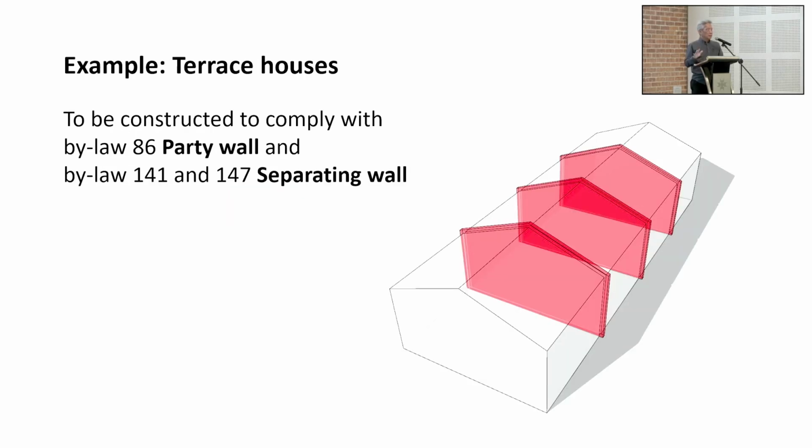But to summarize, to make it very, very simple, take for example a terrace house. For a terrace house, there are no compartment limits to a single residential building, right? Doesn't apply, no compartment limits. So there are no compartments in a terrace house. Inside it will all be partitions only, and you don't have anything in your house that will be picked up by UBBL 139, is it? You're not going to have lithium ion storage, an ESS room in your house, right? Nowadays, maybe you have.